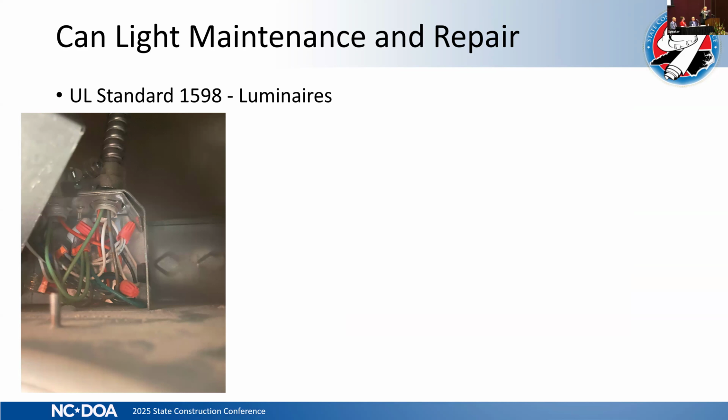Now, I cannot put my 2 hands through a 6-inch opening and keep my eyes on that box. It's not safe to ask an electrician to stick their hands above that ceiling and to open up a 277-volt box that you can only put one hand on at a time. That's just not safe.